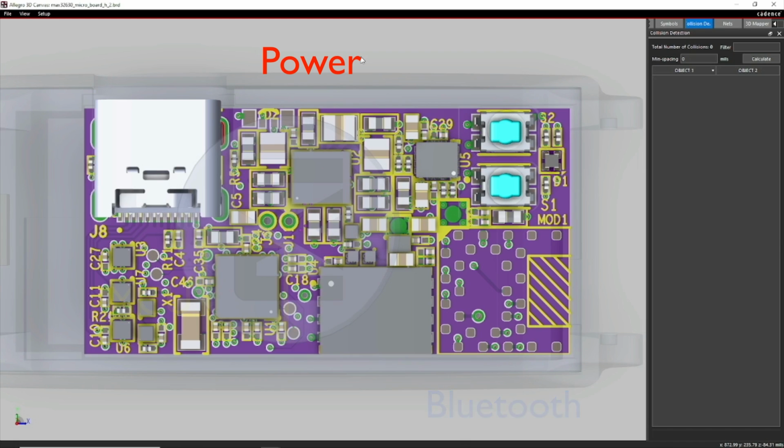A somewhat centralized approach is ideal for many PCB layouts for power, as that reduces inductive loops on all traces or areas, therefore reducing the impedance of any given power trace. Reduced impedance on those power traces means that you'll get a lower voltage drop across that trace when current flows through it. And maintaining your voltages is very important when it comes to power.